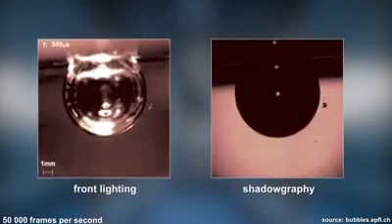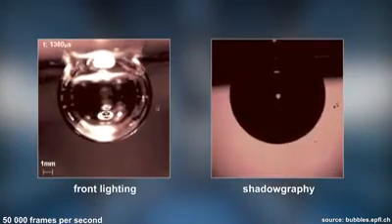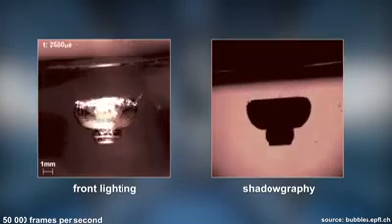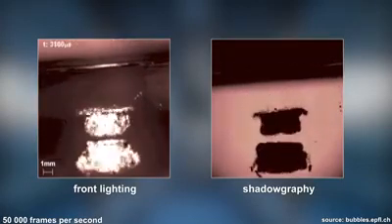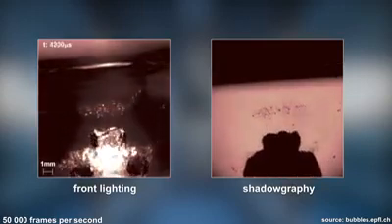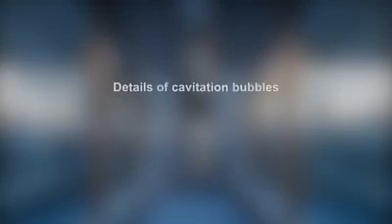Because liquid water occupies many thousand times less volume than vapor, the bubble implodes. It first assumes a ring shape. Shock waves and a strong microjet are the result of a collapse. Let's go through the whole process again.